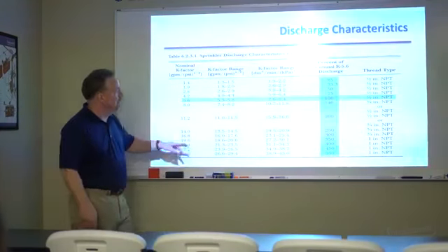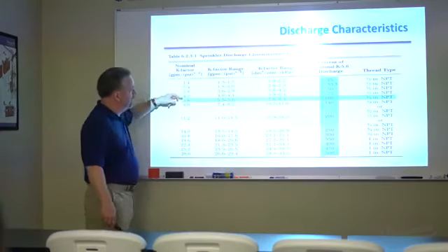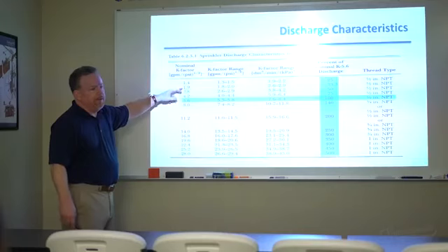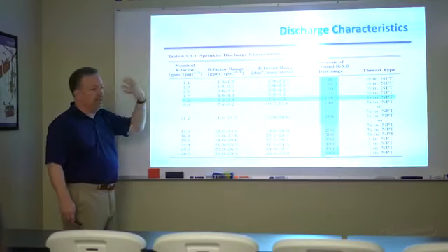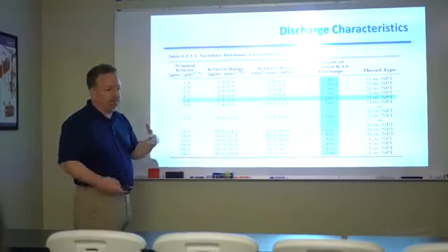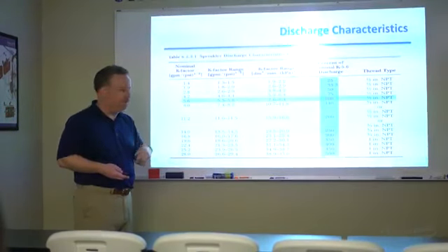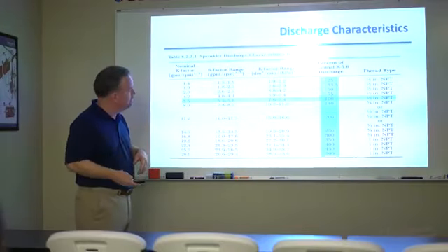But we can also see that we have smaller orifice sprinklers, and they're designed to deliver an equal amount of water with a smaller K factor, same pressure, if you shrink that K factor.